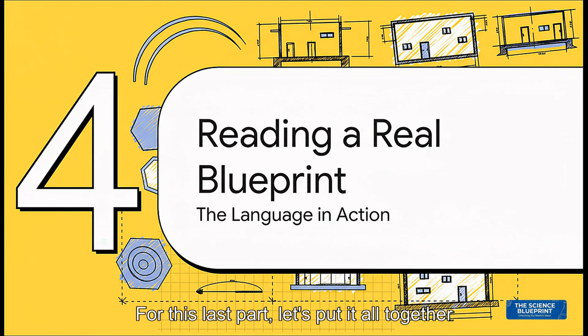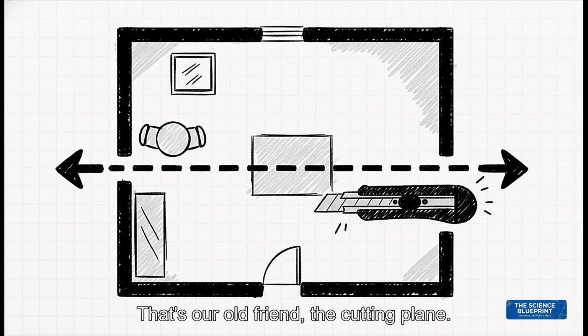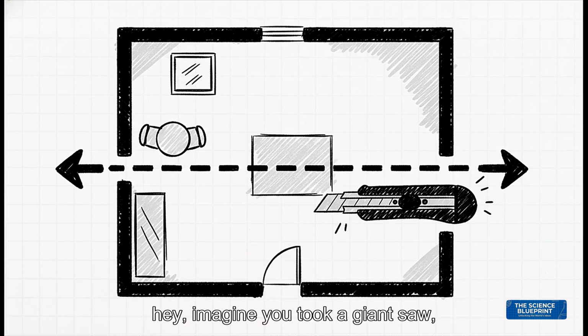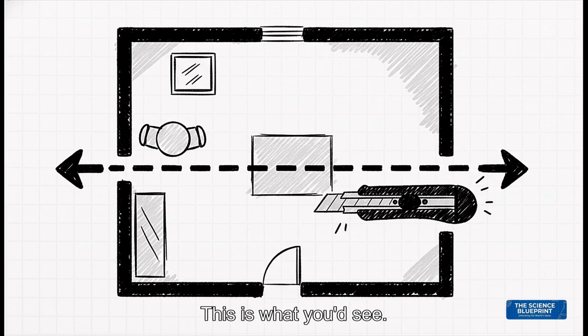So, we've talked projection, we've talked curves, we've talked slicing things up. For this last part, let's put it all together and see this language in action on a real architectural drawing. Okay, so when you look at a floor plan and you see a big, bold line like this with arrows on it, that is not a mistake. That's our old friend, the cutting plane. It's basically a note from the architect that says, hey, imagine you took a giant saw, sliced the building right here, and are looking in the direction of these arrows. This is what you'd see.